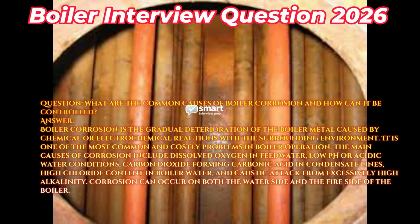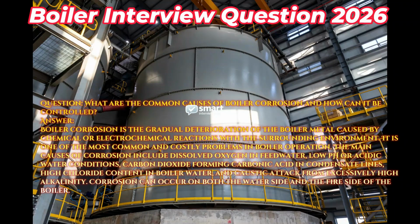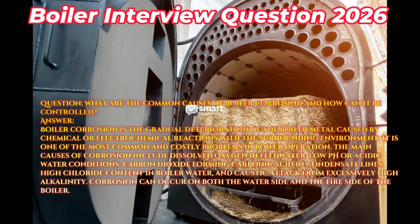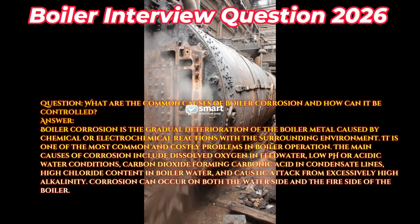The main causes of corrosion include dissolved oxygen in feedwater, low pH or acidic water conditions, carbon dioxide forming carbonic acid in condensate lines, high chloride content in boiler water, and caustic attack from excessively high alkalinity. Corrosion can occur on both the water side and the fire side of the boiler.